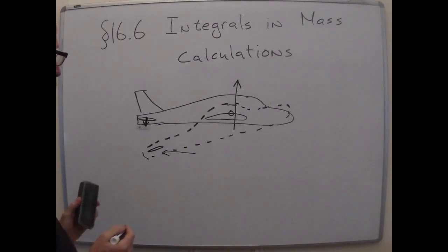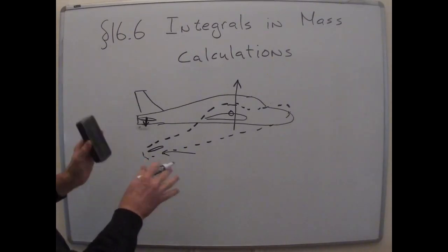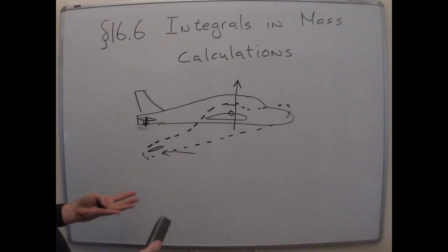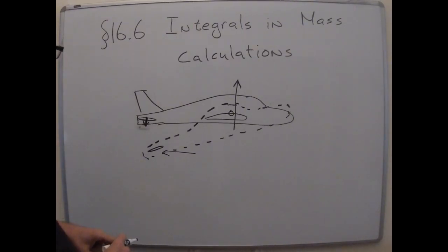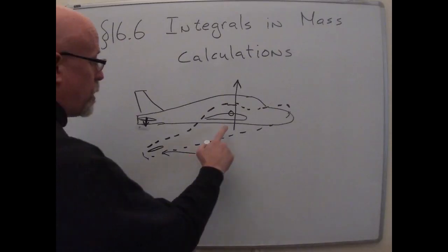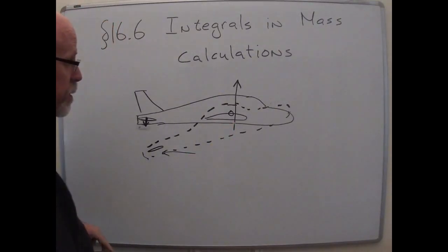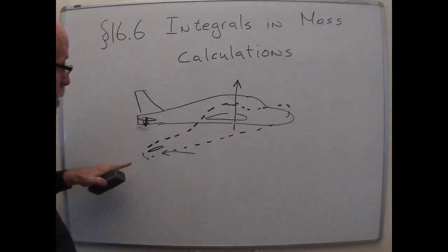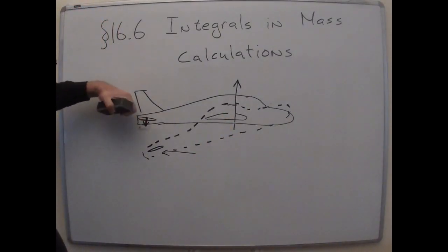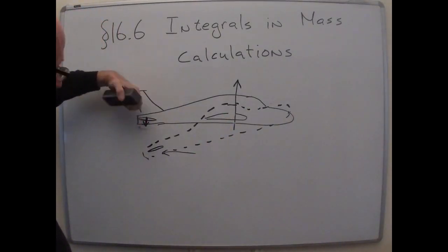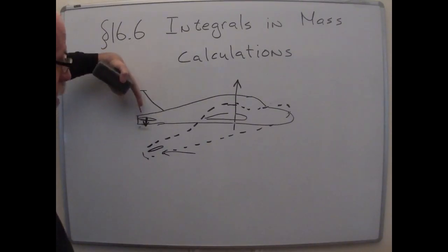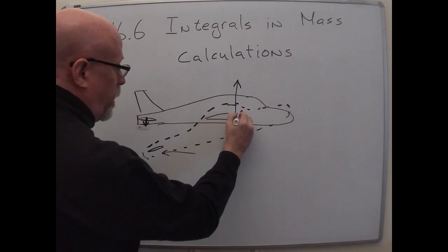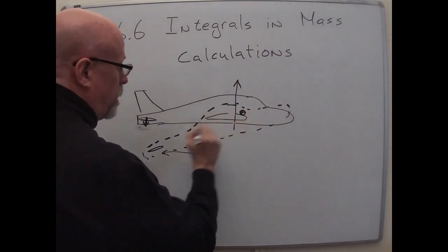And if you put stuff in your airplane, like people or luggage or the fuel, in such a way that you get the center of gravity on the wrong side of the center of effort from this thing, actually where I've sort of drawn that pivot spot is the wrong side. You want this to be necessary for there to be downforce from the elevator, which means that the center of gravity needs to be out there.